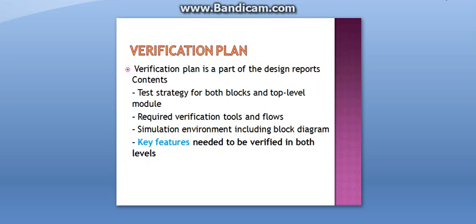Verification plan is very important. It is a part of the design report content. It includes the test strategy for both the block and top level model. The verification plan requires verification tools and flows, and the simulation environment including block diagram. It lists key features needed to be verified in both the block and the top level. Because of the verification plan, there is a clear criterion to determine whether the verification is successfully complete.